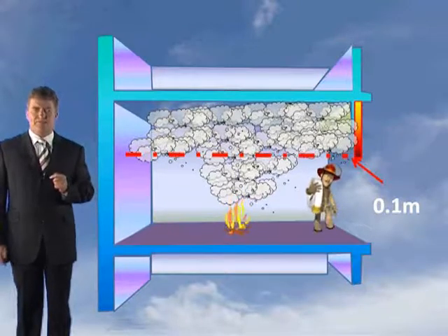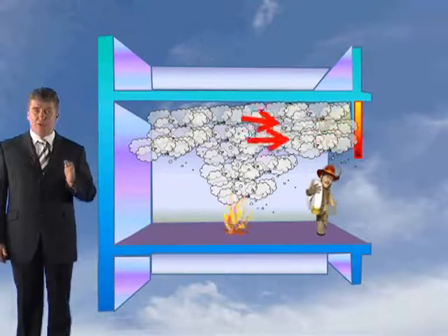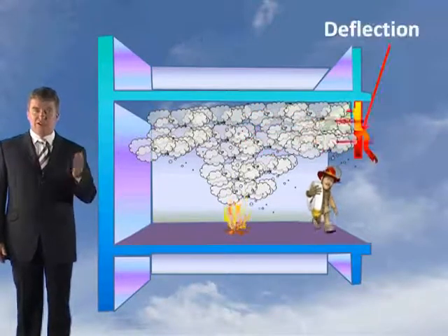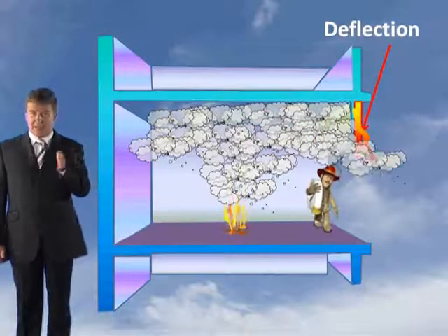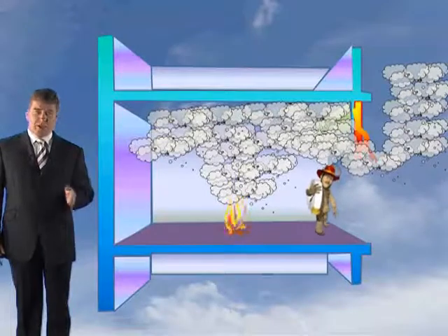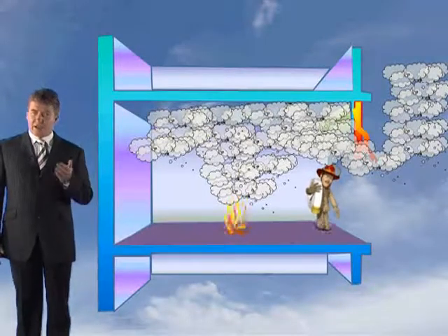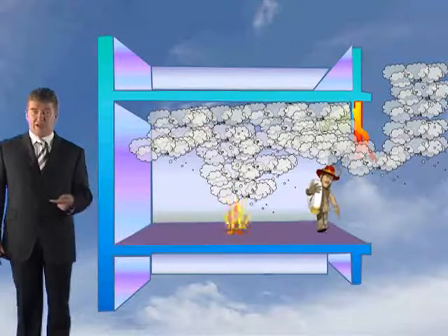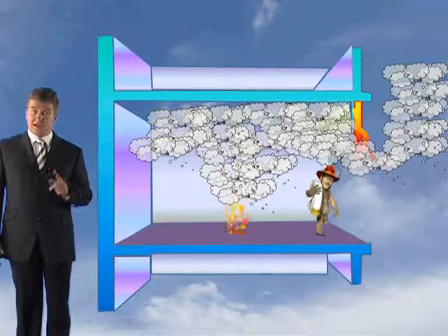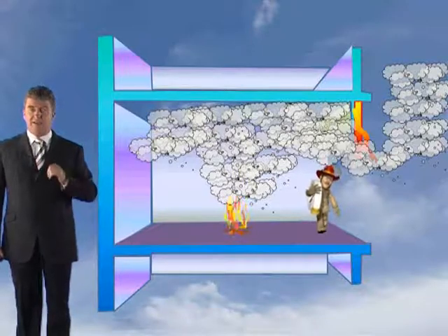Now, the pressure of the hot gases acting on the smoke curtain will cause it to deflect from the normal vertical hanging position. That horizontal deflection of the curtain causes the bottom of the curtain to rise, which could lead to leakage of gas underneath the curtain if the rise takes the bottom of the curtain above the base of the gas layer. So as long as it goes above the gas layer, then obviously it's going to cause leakage.